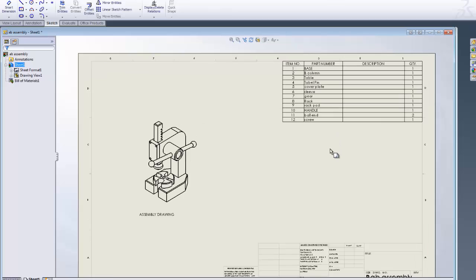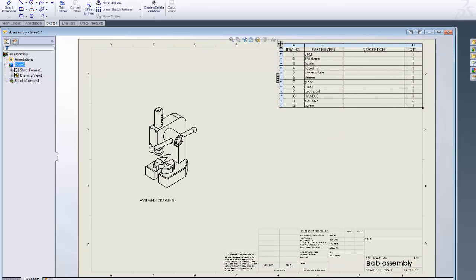Now once my title block is loaded with my bill of materials in there, I can now go in and use my text and add in the description, as well as modify any quantities that I'd want to choose. And if we remember, we have these cap pieces here. There are 2 of those, and they're loaded there. The description would contain things like your finished material, material that you're going to make it out of, if it's a purchased item, the catalog and the location where they purchased that.